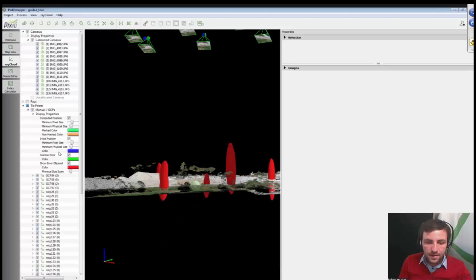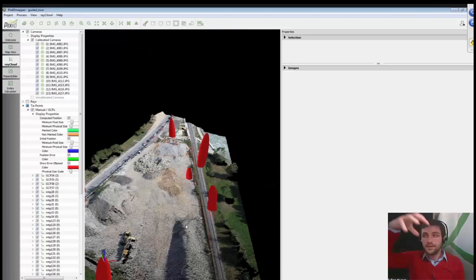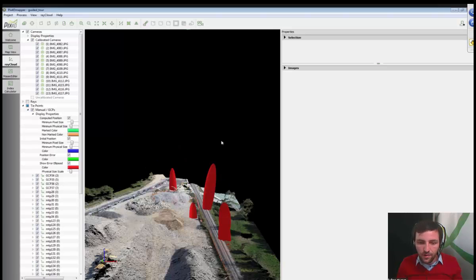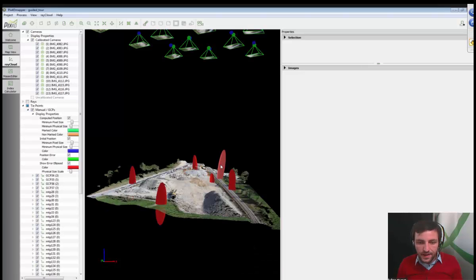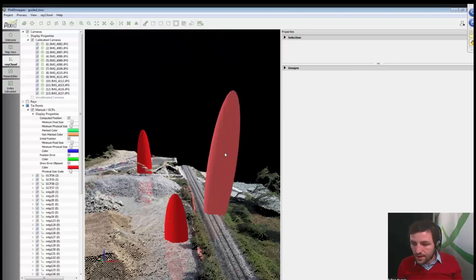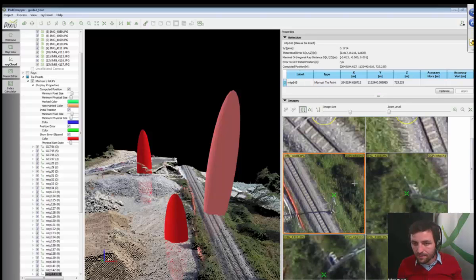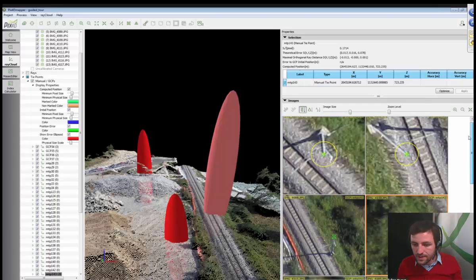Here we visualize how much error potentially there could be on this type point. It's not really the correct scale, so the error here is not an error of 100 meters, but it gives you a good assessment that this point that I just clicked here is not defined as well as the point which was clicked previously in another session just there. So it really gives me an indication that when I did my clicking, either I haven't selected enough images or I haven't done the selection correctly.